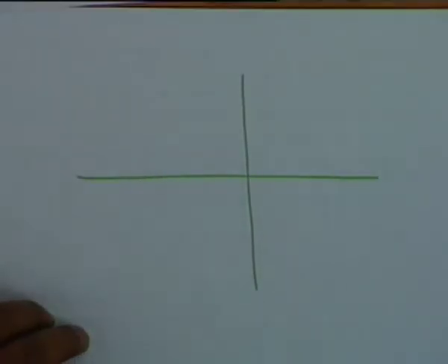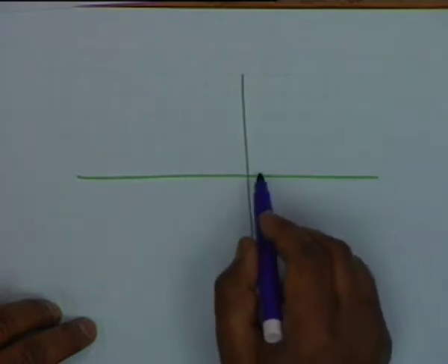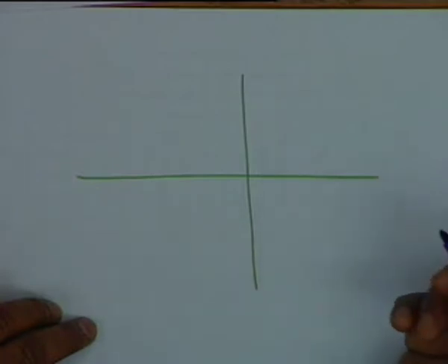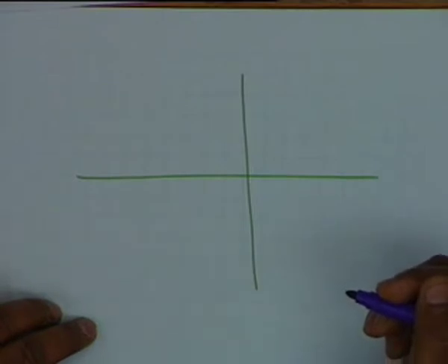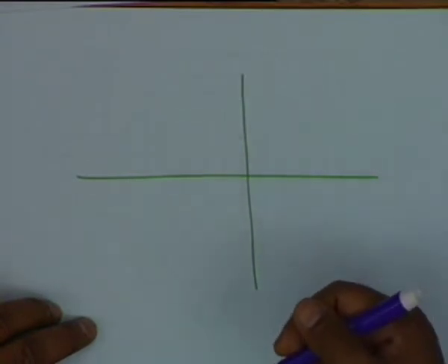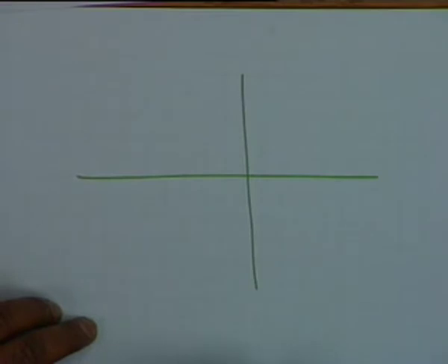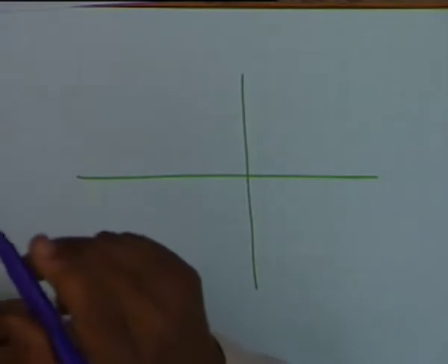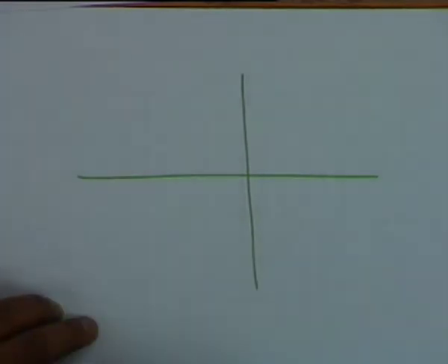A Zener diode, as I said, can be worked as a normal diode in the forward biasing condition. That is, in the forward biased condition, you can represent it by a switch with a threshold, a dynamic resistance and a reverse saturation current. All this applies under normal conditions. A Zener diode is not operated under normal conditions. That is not its purpose.